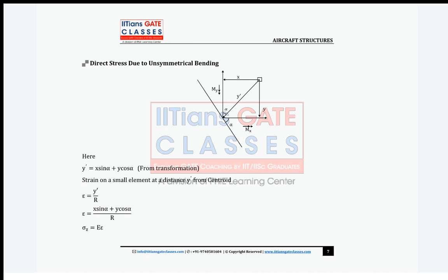We know, right? The strain is what? Curvature times perpendicular distance, right? Curvature is nothing but what? 1 by r, radius of curvature. You can say y dash by capital R.